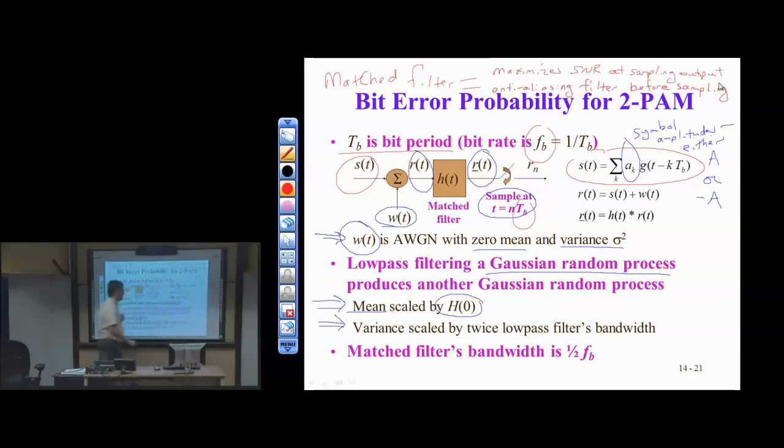The way that we define it here is that the cutoff frequency, which is that value in the transition band, maybe half the amplitude in linear units, or the 3 dB point if it's power, 6 dB point if it's amplitude, below passband, is half the symbol rate, or half the bit rate. Now from a signal processing perspective, we tend to put the stop band frequency at half the sampling rate.